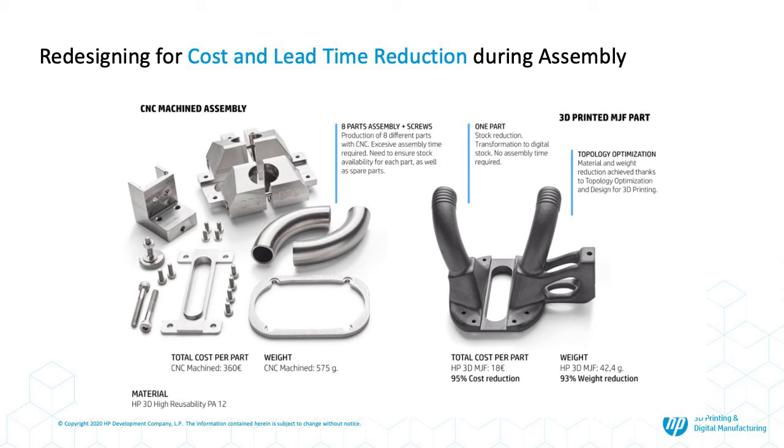And they were essentially able to optimize the flow for the tubes that you see here, which improved the performance of the component itself. And with any fluid tightness or air tightness application, as you can see, being able to 3D print this in one component enabled getting rid of all of these joints and junctures that you have in the CNC machined component, which would result in air leakage potentially.